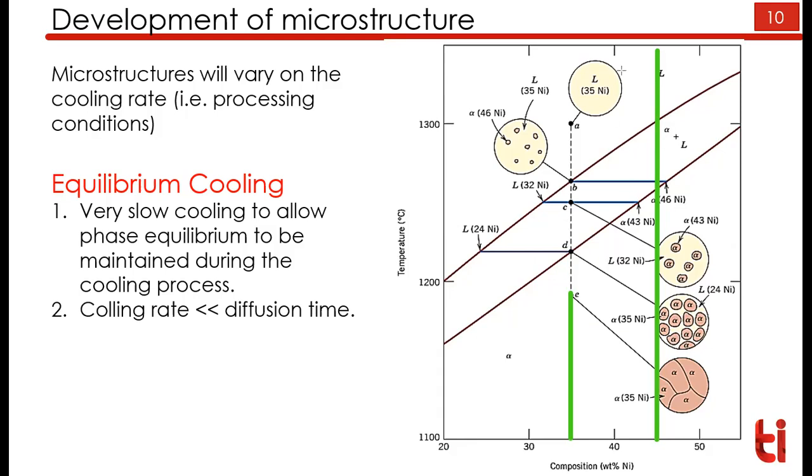Then you have to show systematically a schematic diagram. One point you should take in the liquid region, one point on the liquidus, one point in the two phase region, one point on the solidus, and one point in solid. So total 5 points you write and draw in this schematic diagram and explain it.